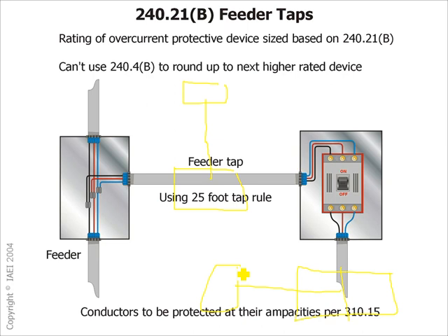As far as this tap is concerned, this doesn't exist, because you're protecting it. This conductor is protected, like 100 amp, so you have your full protection here and you can continue tapping again. But here's the tap conductor, this is the tap, and I can't tap this tap. Anybody have done that? Typically, I've never seen it where you go here, circuit breaker, come here, tap again, but you wouldn't do that. But you can though.